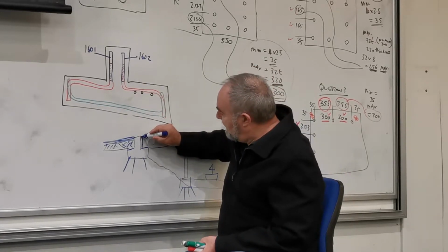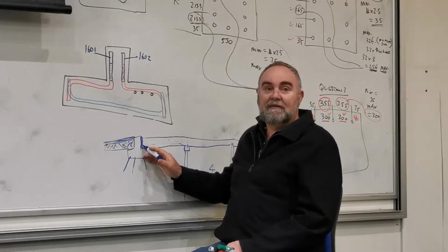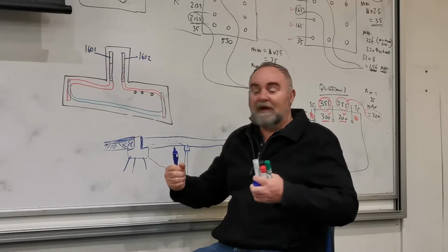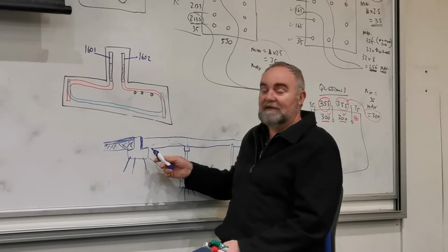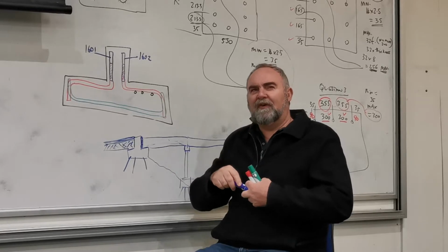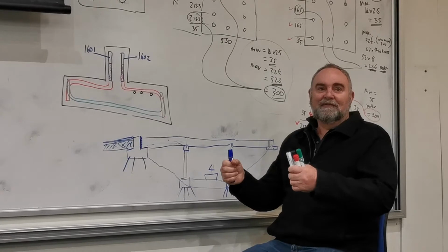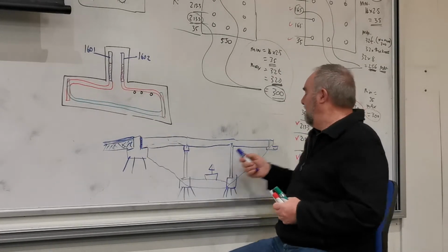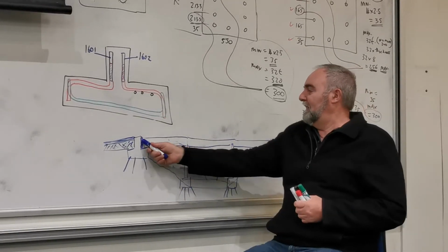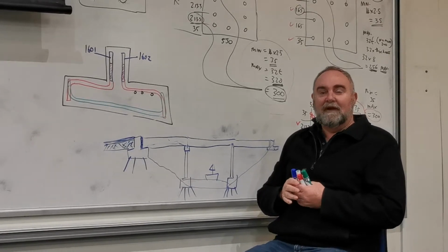In here, they also put a flexible compound, so that obviously with the concrete expanding and contracting, you're not going to come along and find there's a big gap there. But you always find when you're driving onto a bridge, even anywhere in New Zealand, there's a bit of a dunk as you go over that bit, and a dunk at the end, right? And sometimes in the middle as well, but normally there and there, which is the bit that takes up the expansion, all right?